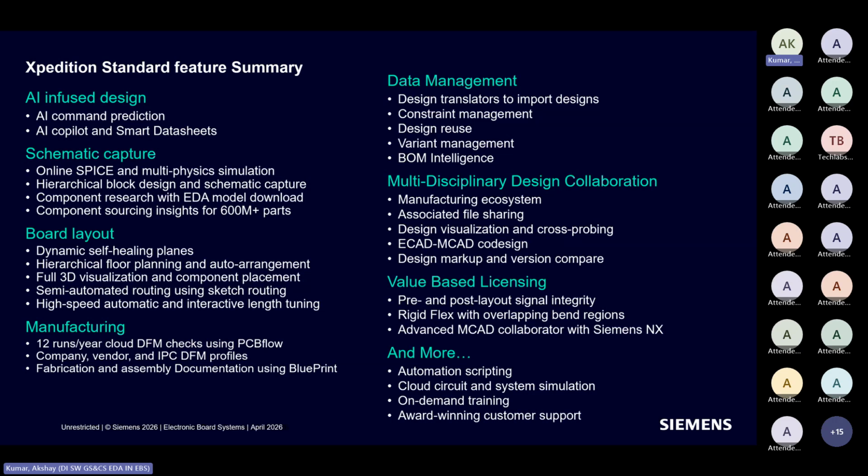Because we have a migration wizard which will allow you to migrate your existing designs to the Expedition flow, right? Then of course, BOM intelligence, which we discussed. Then you have an ecosystem where you can share files with a person for review and feedback. That can be in terms of ECAD, MCAD, or any design markup. And if you have two versions, you can also compare them graphically, like schematic and PCB. So that is also quite possible here, right?